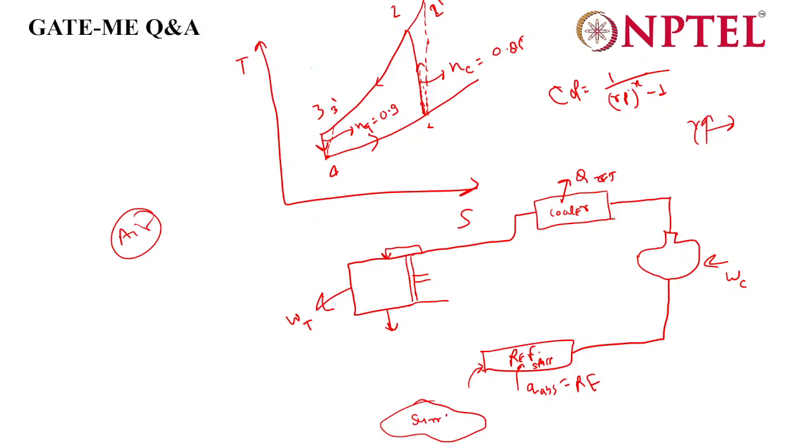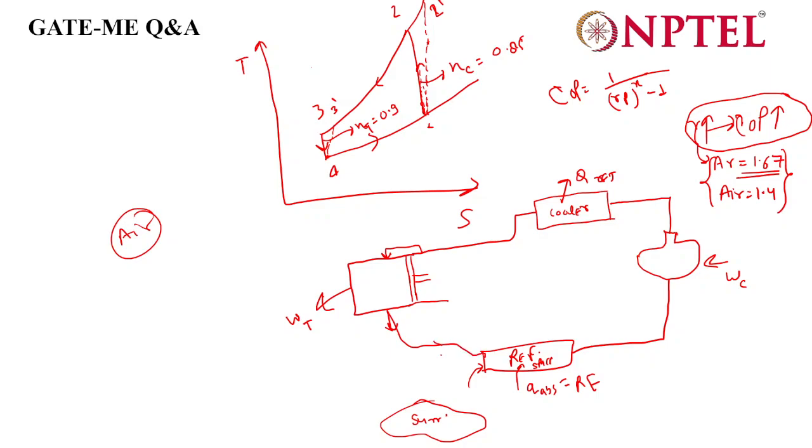If this increases, then what would be the effect on COP? Increases, sir. If gamma increases, COP will increase. So what is the gamma of argon? 1.67. So it increases, and for air it is 1.4. So if argon is the working fluid, then we cannot go for the open cycle, but with air we can. Now it is clear what is the Joule cycle and what is the Brayton cycle. It will become Brayton if we connect it.